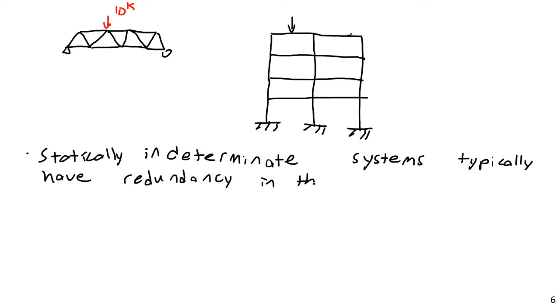You said the top of a truss has to be in tension and the bottom has to be in compression? Vice versa. The top will be in compression, the bottom will be in tension. Typically, under typical conditions. Now, there are a lot of caveats to that, like if I moved this roller here, so there was a cantilever, part of the truss was cantilevered or something, in that case, it would be very easy to end up with negative bending moment.